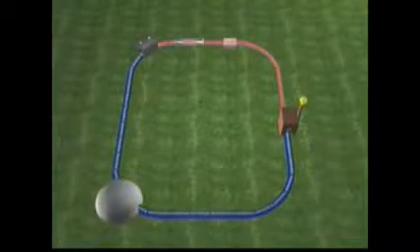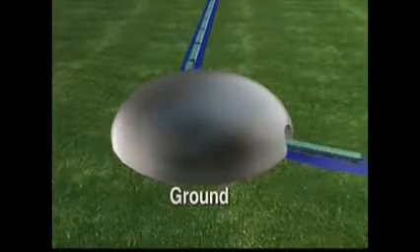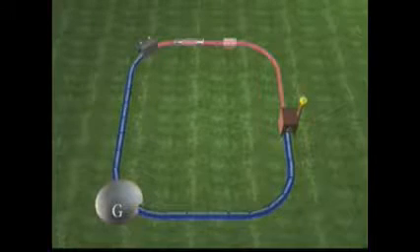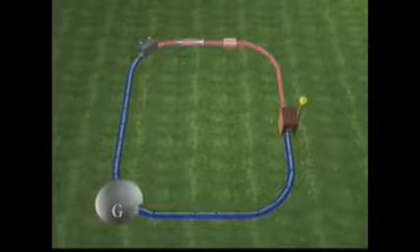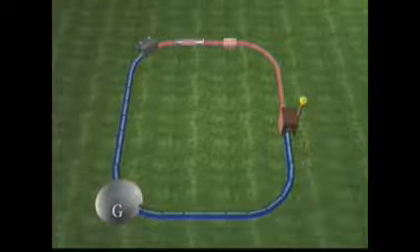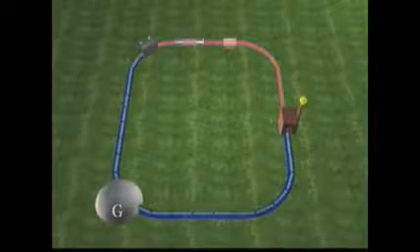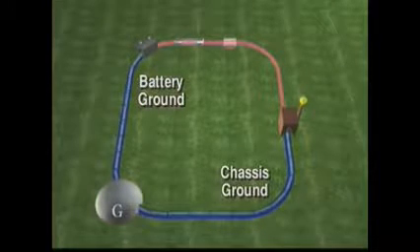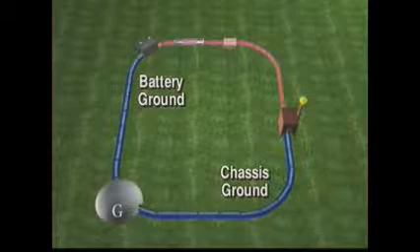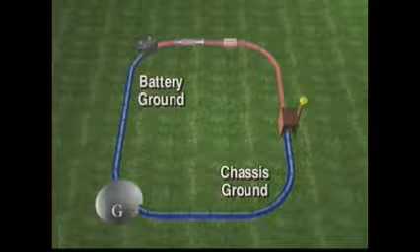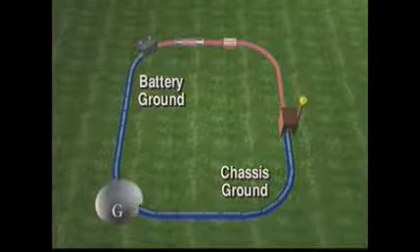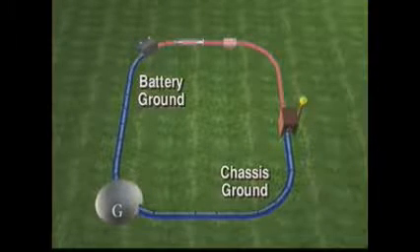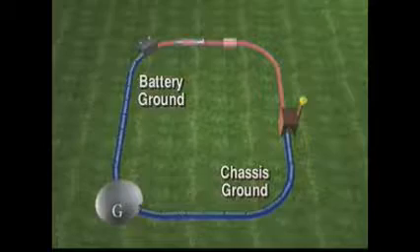The last and final piece of our circuit is the ground. The ground is the current flow path going back to the negative battery terminal, making the circuit complete. Current cannot flow unless we have a complete circuit and voltage. The blue section of our circuit represents the body chassis and battery ground cable. Remember that the freight cars come back to the battery for more voltage. When a circuit is operating, current flows back to the battery through the ground side.